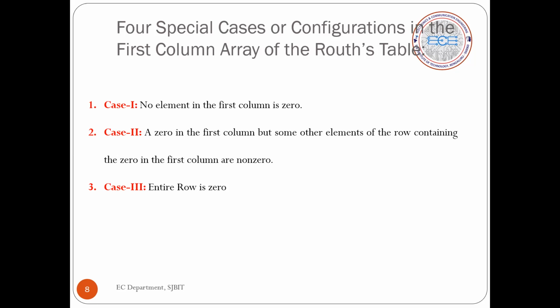It will not always be the same situation; we will find different situations, and as the situation changes, we change the procedure to fill up the table. The objective is to finish the Routh-Hurwitz table, and only then can we comment on the stability. We come out with 4 standard cases here, and case 2 has 2 different solutions inside.